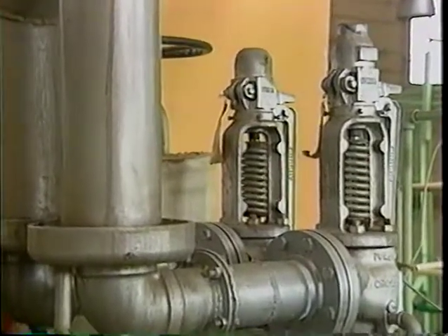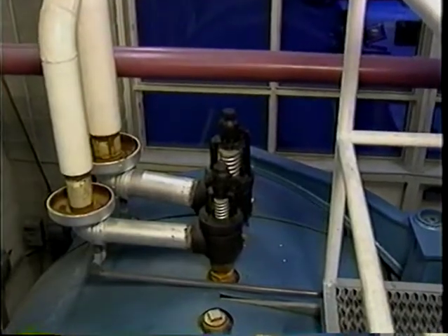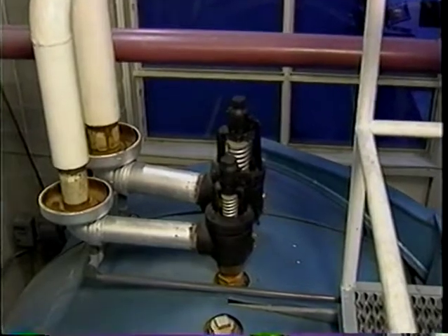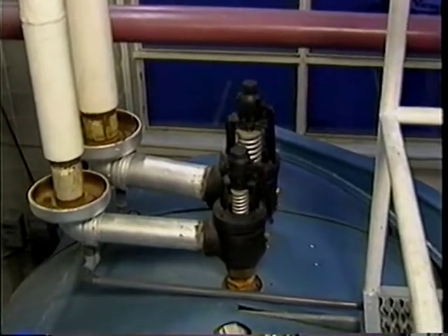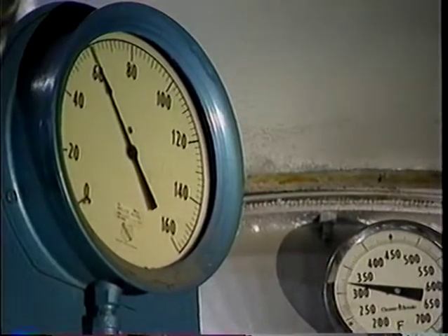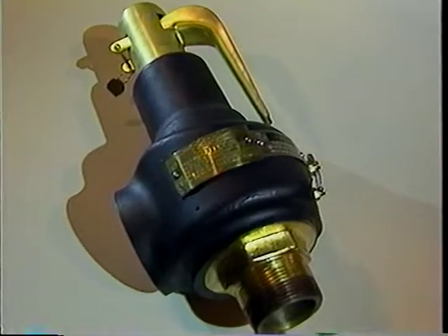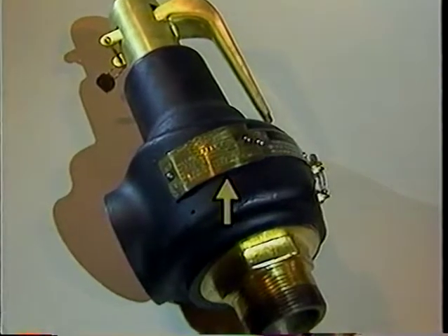Safety valve capacity is measured in the amount of steam that can be discharged per hour. The safety valve will remain open until sufficient steam is released and there is a specific amount of drop in pressure. This drop in pressure is the blowdown of the safety valve. Safety valve capacity and blowdown is listed on the data plate on the safety valve.